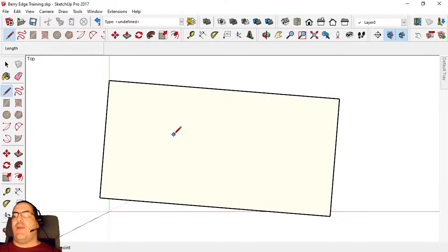In 3D software, faces and edges are separate things. So that's a face, that's an edge. And you can see there it changed to a red square. So it tells me that I'm on the edge, or the line round the edge, and there I'm actually on the face itself. On the edge, you also get different icons for different parts of the edge, depending on whether you're in line with things or anything like that. So if I move this down the edge, at some point I will hit the midpoint, and it will turn into a blue circle. There we go.